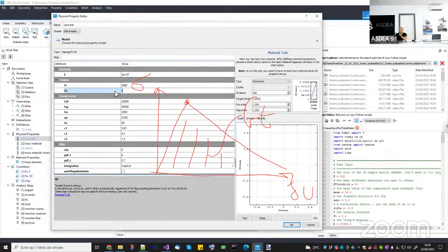The fracture energy is the amount of energy required to open a crack of unit area. So it actually has the dimension of a work, for example, joule over meter squared. But this one is actually a force times a length, so force times a length over an area, over a length squared. So it turns out that it has the same dimension of a stiffness, so force over length, if it is the area underneath the stress displacement curve.